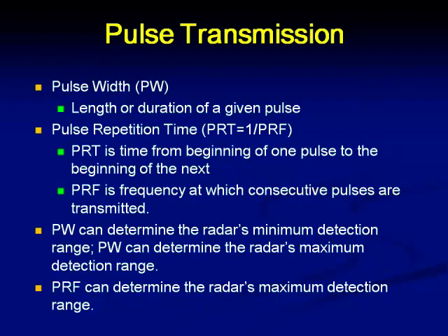The reason the radar is not able to detect close targets is that when the transmitter is ready to send the pulse, the receiver is not connected at all, and hence the signal reflected from a close by target will not be received by the receiver. That can be considered a drawback of this system, but there are several other advantages by which we prefer to go with the pulsed systems.